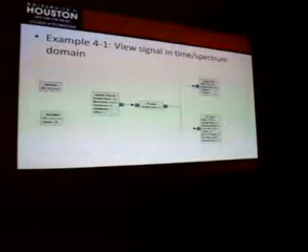The first step is adding blocks to the diagram and setting the parameters. The second step is connecting blocks with each other and saving the file. Then the computer will generate a GRC file, and you can also convert it to a Python file. The third step is executing the flow graph and receiving the signal by using the USRP2 receiver we designed before. And here are some simple examples.